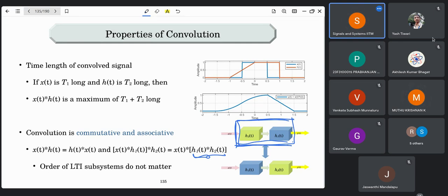And sir, when we give an input to a system, what happens inside the system so that we get a particular output? Think of a system as something which contains some kind of memory. When you feed in a signal, it will instantaneously see the current value, scale it, either attenuate or amplify it, and store it in the memory. The output that it produces is a scaled sum of all the values that it has stored in the memory.